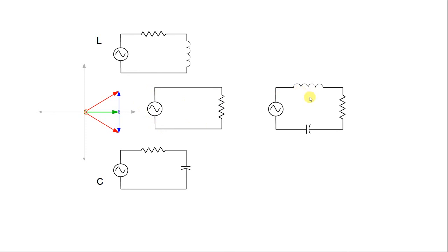Now, I said that our inductive loads are things like motors and transformers. Well, motors are not always running, they're going on and off. It would be rather impossible to always be adjusting this capacitive side to get to a purely resistive load, but we can bring an inductive load closer to the mark of a purely resistive load by adding capacitance into the load.